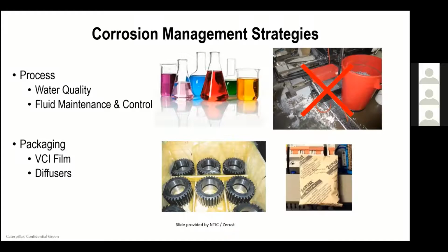And so probably what's not known to many people is that it's really important to package these parts. A lot of times if you buy a part at an automotive store, you'll see it wrapped in paper, or you'll see it come in a colored film. That colored film has actually been treated, or is impregnated with amines in most cases. When you wrap the part or close the container, the amines in that film or on the paper will microscopically, you won't be able to see it, form roughly over maybe a 24-hour period on that part, protecting it from corrosion.